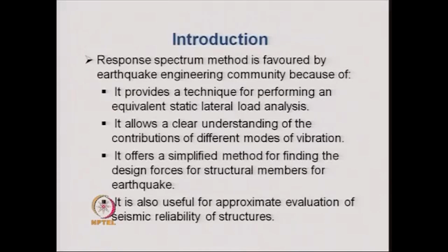The dynamic analysis of a structure is obviously more complicated compared to a static analysis, and therefore, when this entire concept of response spectrum method of analysis was developed to find a simplified equivalent static lateral load analysis, the method really became very popular.